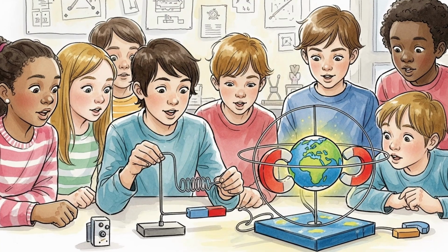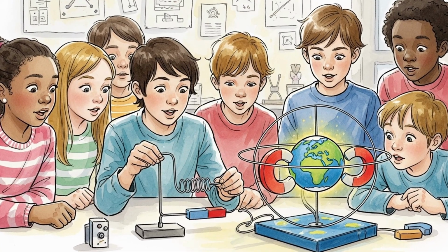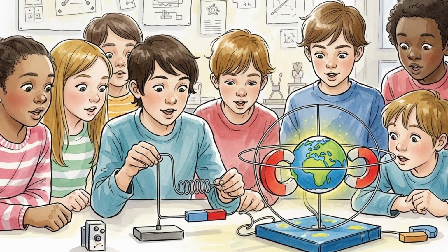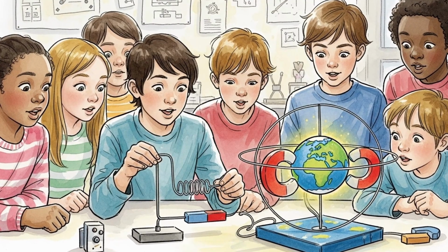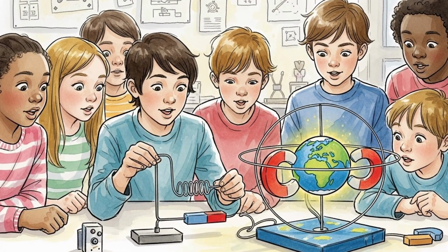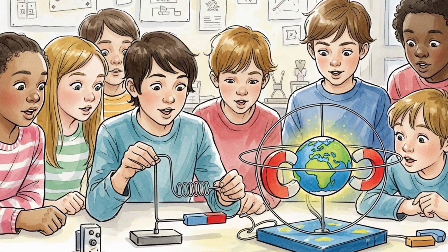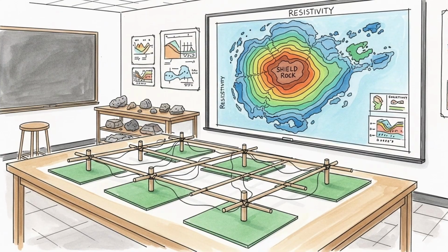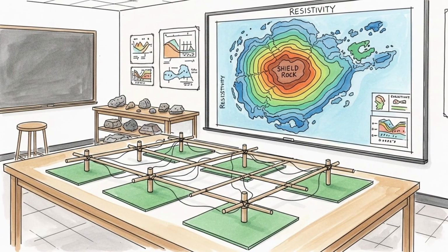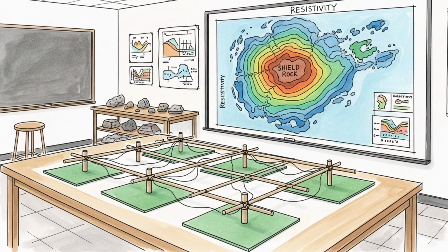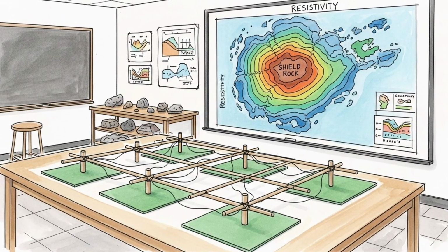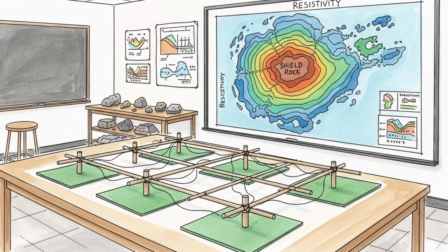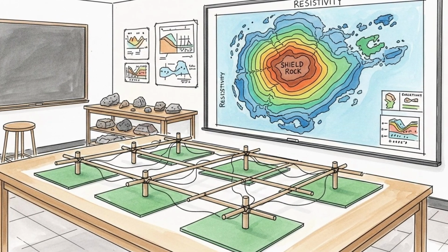Commercial aircraft structure provides some shielding, but it is limited. Airlines manage exposure by tracking accumulated dose for crew and by adjusting routes and altitudes during events. Dispatch and flight operations use alerts from space weather centers to plan polar traffic. When a strong event is in progress, dispatchers consider 3 options. The first is to reroute away from high latitudes.